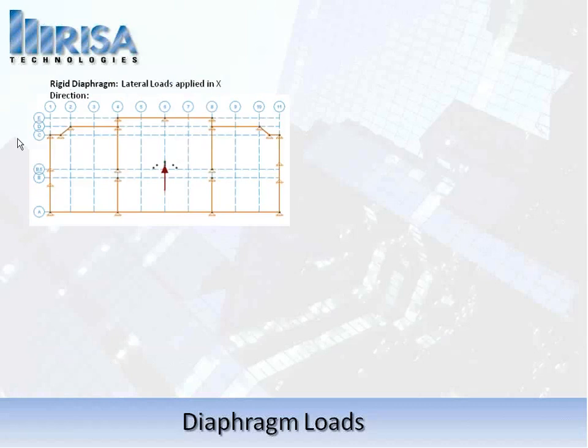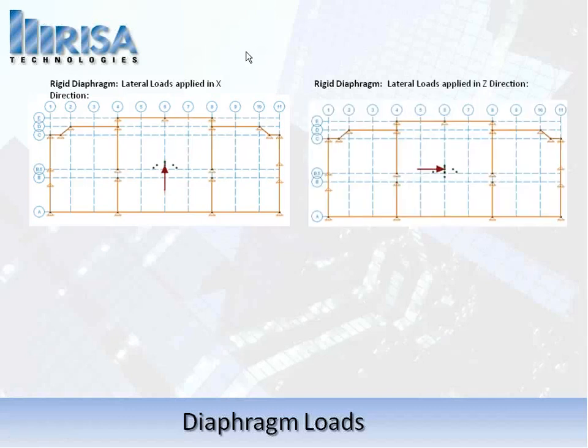And all these little walls here are actually going to be taking their portion of that point load, based on their stiffness. They are all contributing, and the loads go across the rigid diaphragm. They're distributed based on stiffness to the elements that are resisting. That's our rigid diaphragm in the x direction. The same thing happens in the z direction, and we'll open the model and see how that works. Basically, that 1 point load applies into the diaphragm, and then we distribute that load based on stiffness to the lateral resisting system, which happens to be wood shear walls in this model.